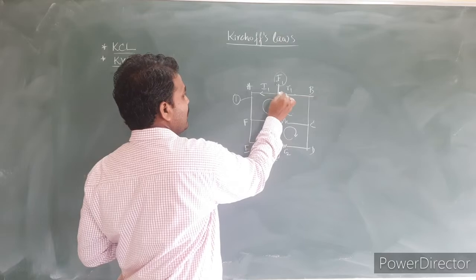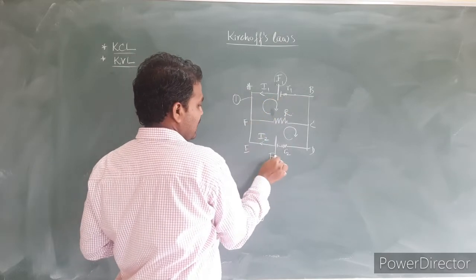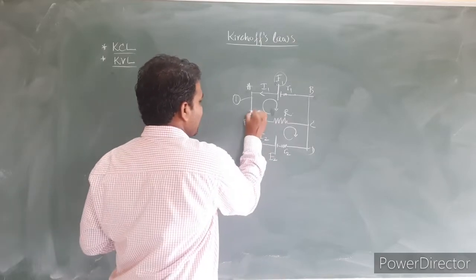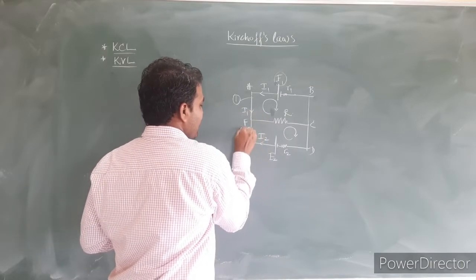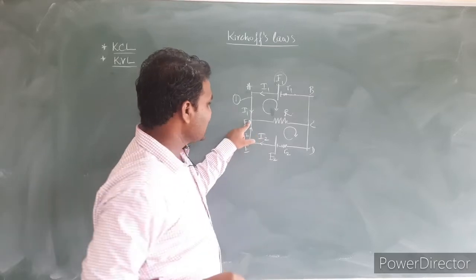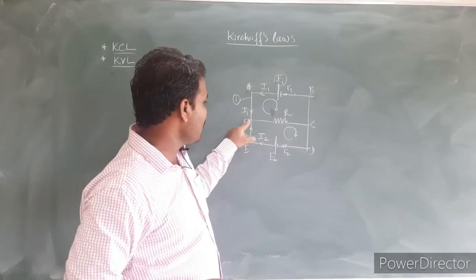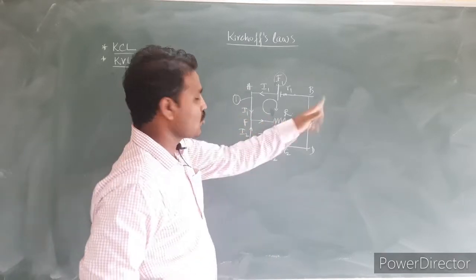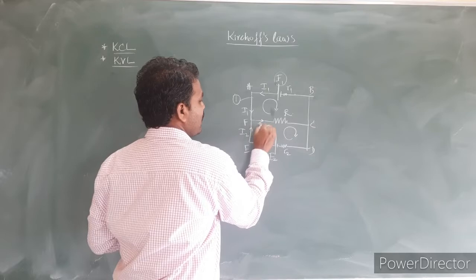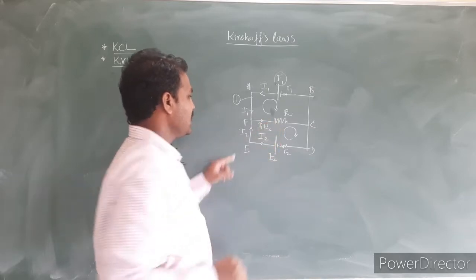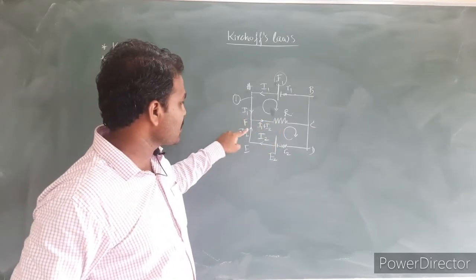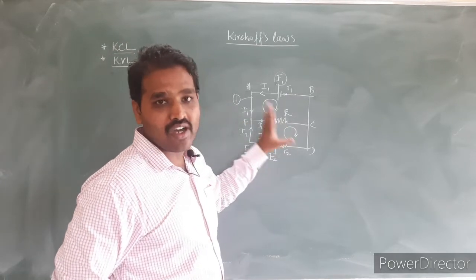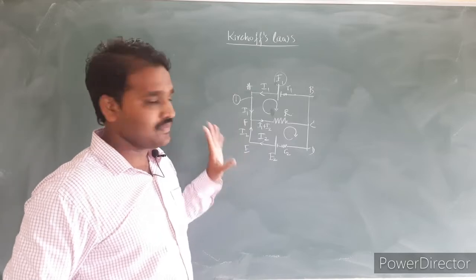Okay. This I1 will come from A to F. Yes. Again here this I2 will come from E to F. So here I have an input current of I1, and here I have an input current of I2. At the junction F, both are input currents. Hence, here it should go out. So here I will have the current of I1 plus I2. The current leaving this junction will be I1 plus I2. So the current passing through resistance R is I1 plus I2. I hope it is clear.